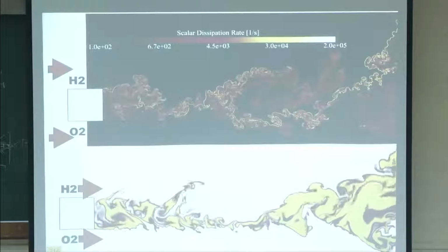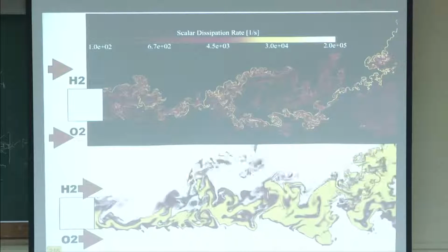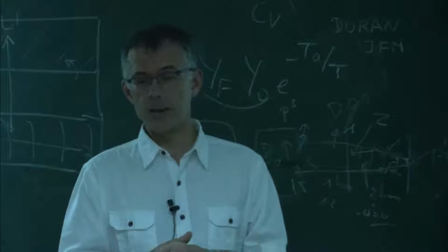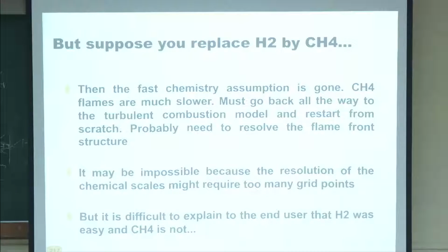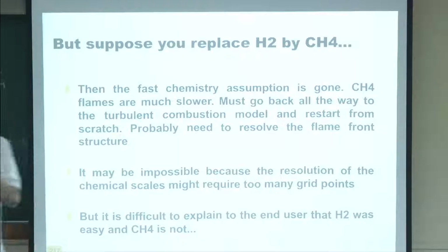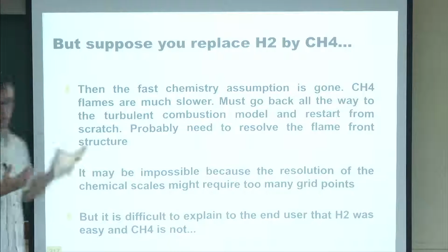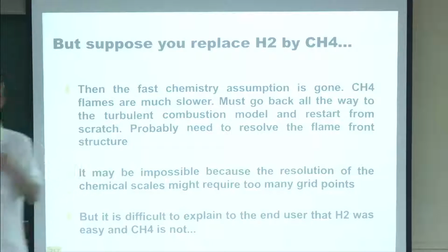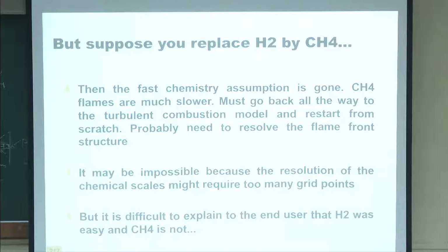But then 2 years later, these guys from the company in France came to us and said, we want to replace now the H2 by CH4. So, okay, that's a good idea, except that CH4 burns much more slowly than H2. And then suddenly, the problem of kinetics, which was not a weak point before, becomes the weakest point of the whole show. Because if you say that the chemistry of CH4 with O2 is infinitely fast, then it doesn't work at all.